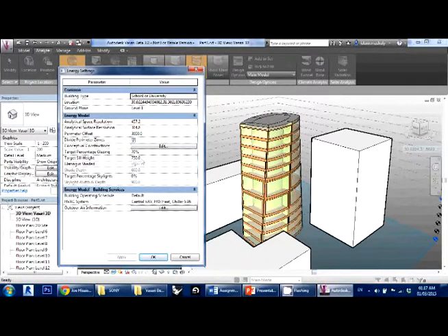Okay, the sill height of the glazing, and whether the glazing has a shading device on it or not. So if we have a shading device, we can tick this button and determine the shading depth, and in the end we have the percentage of skylights. If our building has skylights here up on the roof, we can put any percentage, and we have skylights distributed on the surfaces.